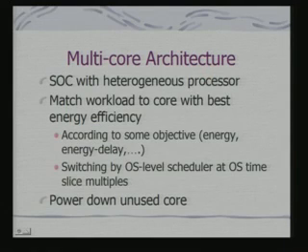The other thing is that today in your SOCs we have already found multi-core architectures, that is, SOCs having heterogeneous processors. And these processors are targeted for doing different kinds of work. So, one of the basic issues involved is to match the workload to the best processor, and best processor from which point of view?